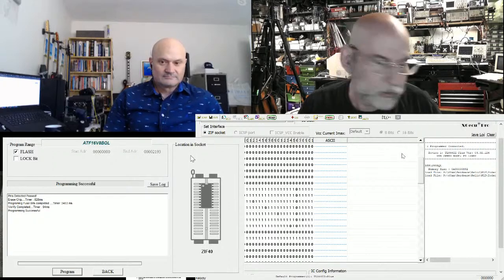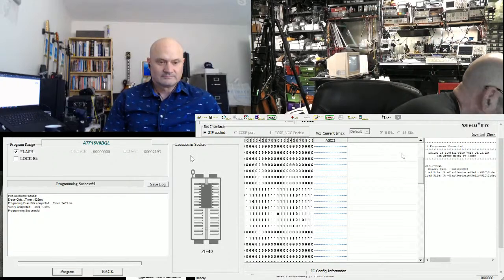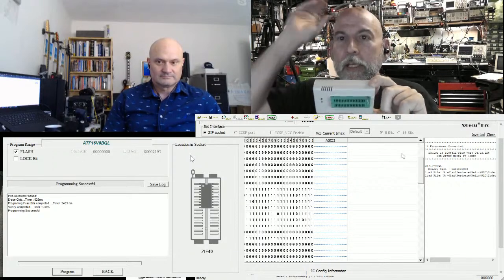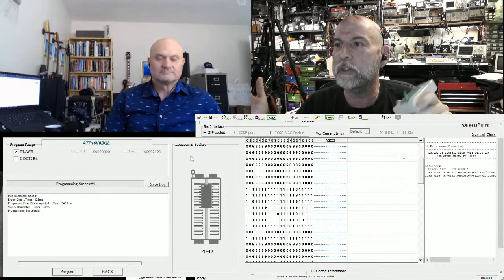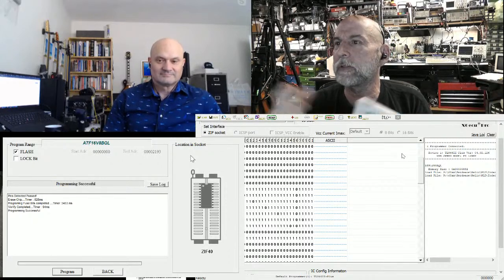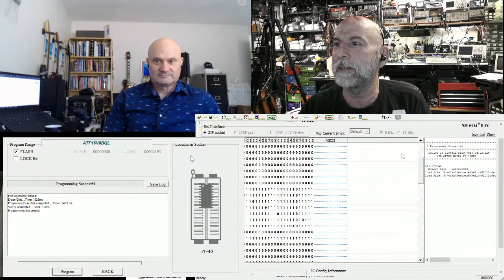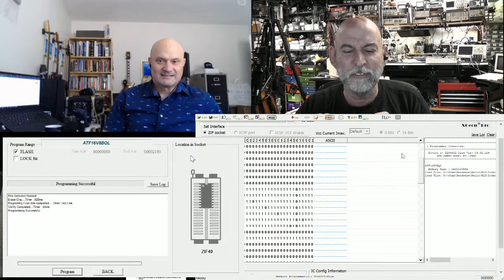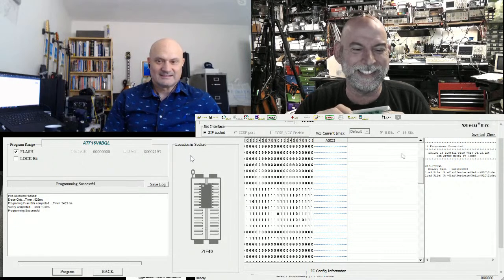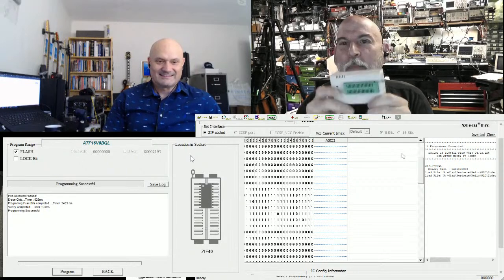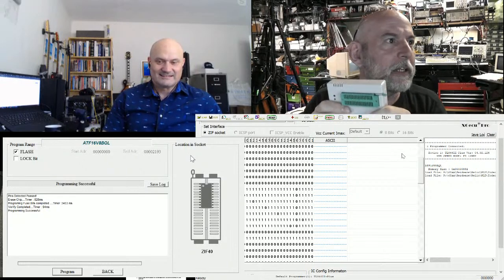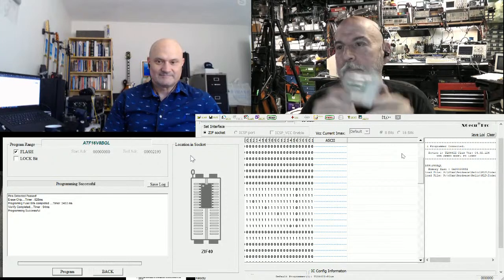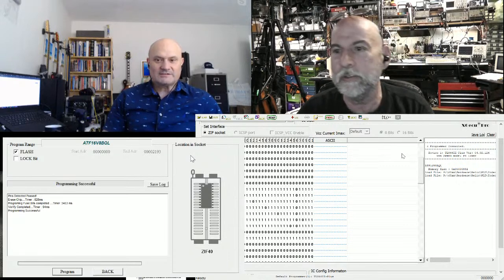And that's where the problem with this older programmer was. This older one did lots and lots of the family, just none that I could get. It did GALs. I can't buy a GAL, not a true GAL these days. GAL used to mean generic array logic or something like that. I just remember it was cranky, but it was cool stuff. But I couldn't do this because I couldn't actually get an ATF16V8BQL in the software for this one.